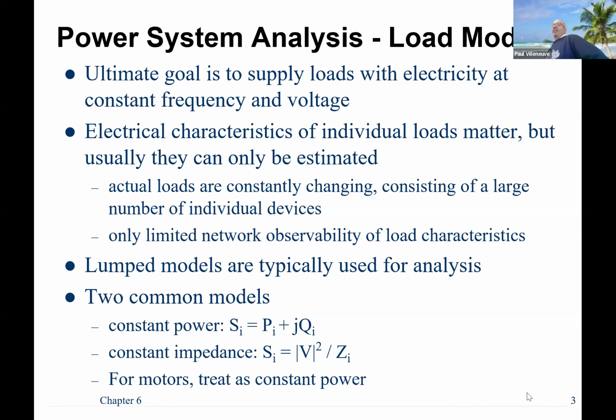Motors, we typically treat them as constant power, because one of the things about a typical induction motor is as it starts to slow down, within reason, it actually draws in more power. So if you try to drop the voltage, it would slow down, but then it's going to increase the amount of power, so it backs back, it increases it back up. So it's a mechanical load, and usually the load is what dictates what it needs, not the speed.